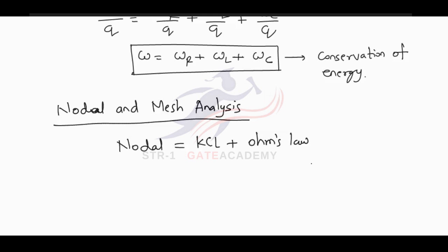That means when you are applying nodal, you are applying KCL and Ohm's law. Then we have mesh analysis. Mesh is nothing but KVL plus Ohm's law.